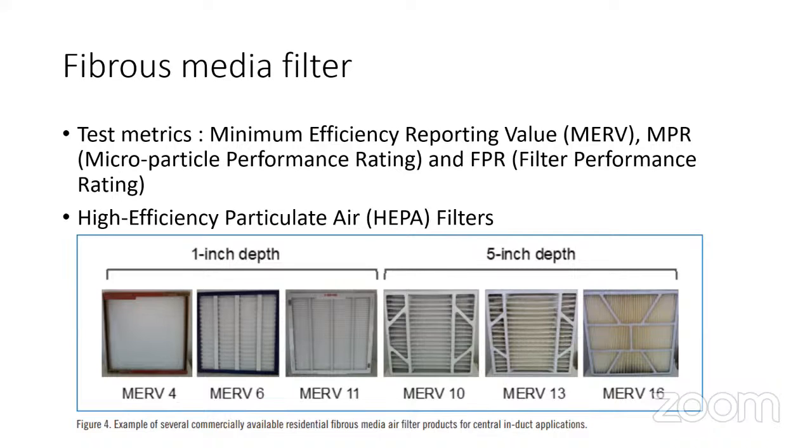Again, there are two different types of fibrous media filters. In one, the material is used as such, and the second variety is where the manufacturer modifies it to have extra electrostatic charge on them so that the deposition is better.